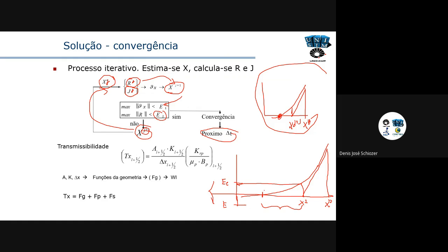So there are some equations in the simulator that have this behavior. They converge very slowly to the solution. So sometimes I'm inside the tolerance for the residual, but I'm still very far from the solution. So the simulation also includes this second term here, meaning that if x0 is very different from x1, then even if I'm inside the residual tolerance, I'm going to do another iteration and calculate again.